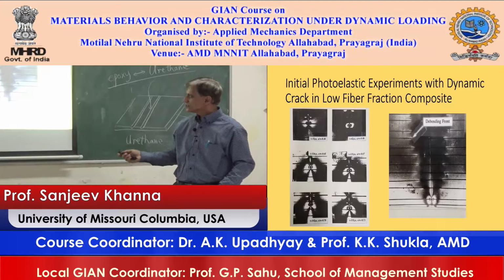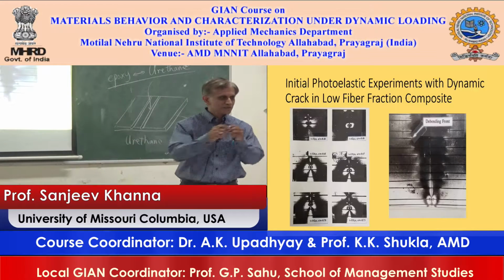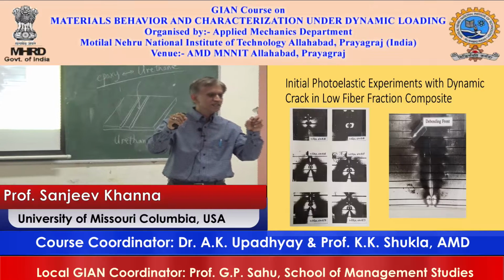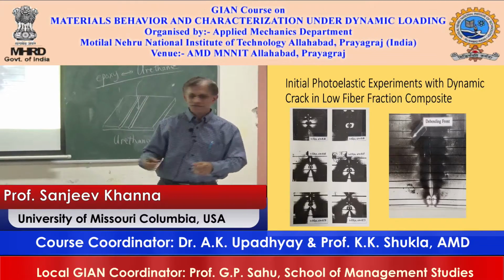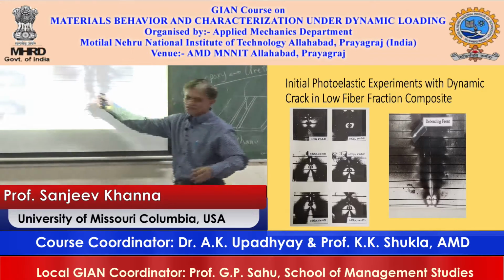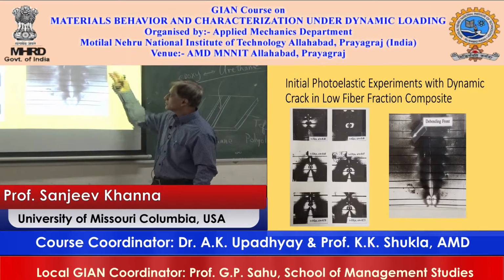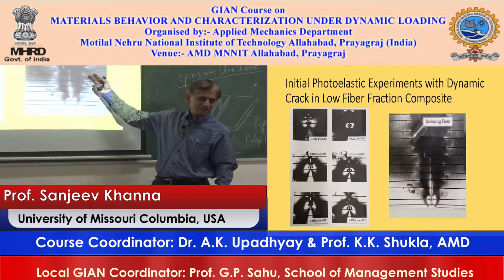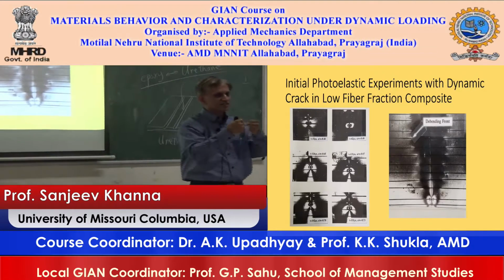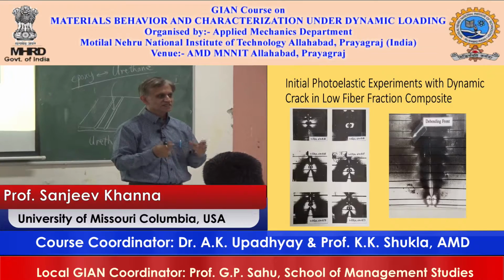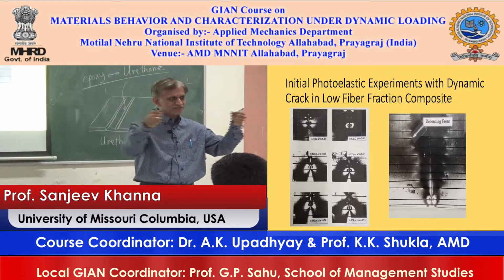Over that length which is debonded, that debonded fiber is stretching now, because here and here I am pulling apart, and this part is all solid material, and this fiber is bridging that gap and it is taking a load. That becomes the gauge length over which the fiber is stretching.